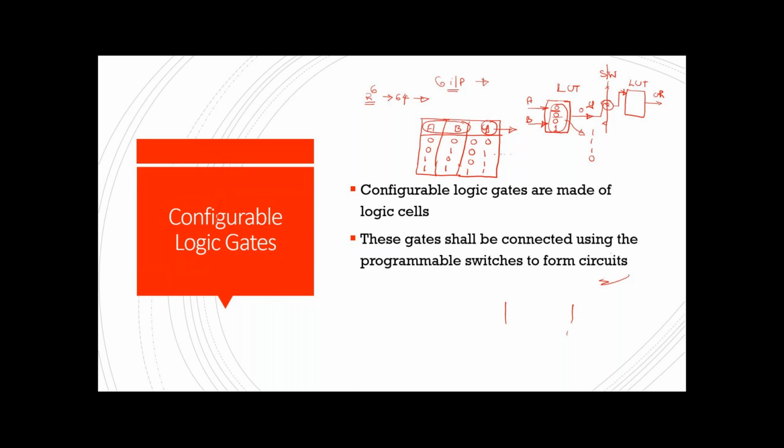So for instance, let me take an example of FFT. In FFT, we have to go with that butterfly mechanism. If you write a simple C code based mechanism and implement it in the processor or GPU, you make it step by step in a flow. It's not something where in one clock cycle itself you're going to get the output. One instruction after another you fetch and decode, and do those computations. But in the FPGA, you can design the equivalent digital circuitry of that entire FFT itself, and make that circuitry work within a few clock cycles compared to your GPU or CPU.